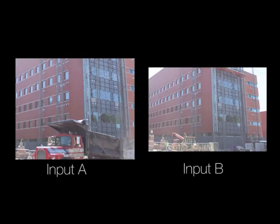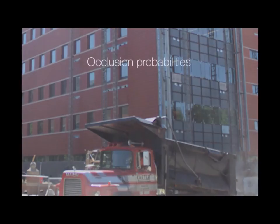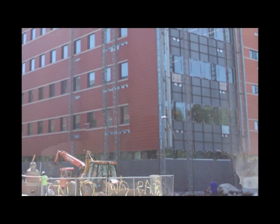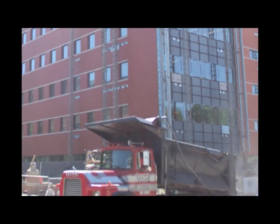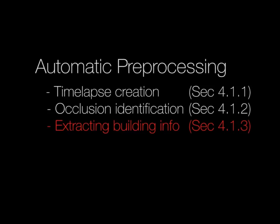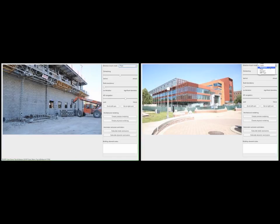Dynamic occlusions are detected by locating moving objects in a view-aligned image sequence. We measure pixel-wise differences in the HSV color space, then smooth and threshold these differences to obtain a dynamic occlusion mask. These occlusions, typically construction equipment, can then either be removed or properly placed over the 3D building model for visualization. Building information models contain semantic information about the structure that our system leverages for efficient selection, annotation, and rendering.